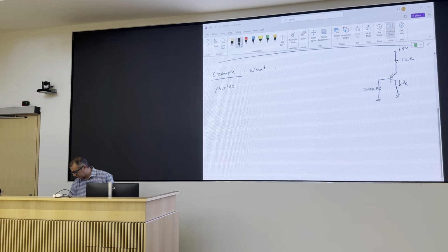Right? So I just have one IC, simple linear equation done. And if you choose the right value for this VDO, if it is a small transistor, you can pick between, I don't know, 2 fingers, 0.6, 0.7 is good enough. If you need to use 3 fingers or maybe a hand, maybe 0.4, 0.5 volts, right? If you can't see it with your eyes, 0.8 volts.